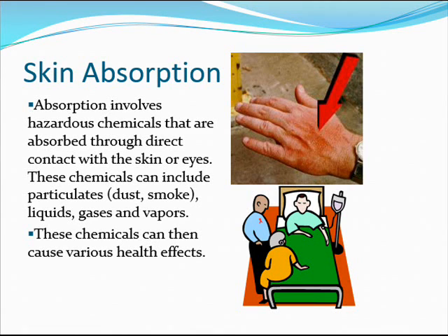Absorption through the skin or eyes can be prevented with the proper use of appropriately selected gowns, gloves, work clothing, and personal protective equipment that covers the eyes, such as full face masks, safety glasses with side shields, and face shields, appropriate for the specific contaminant. And in some instances, a full hazard suit with a head mask is appropriate.